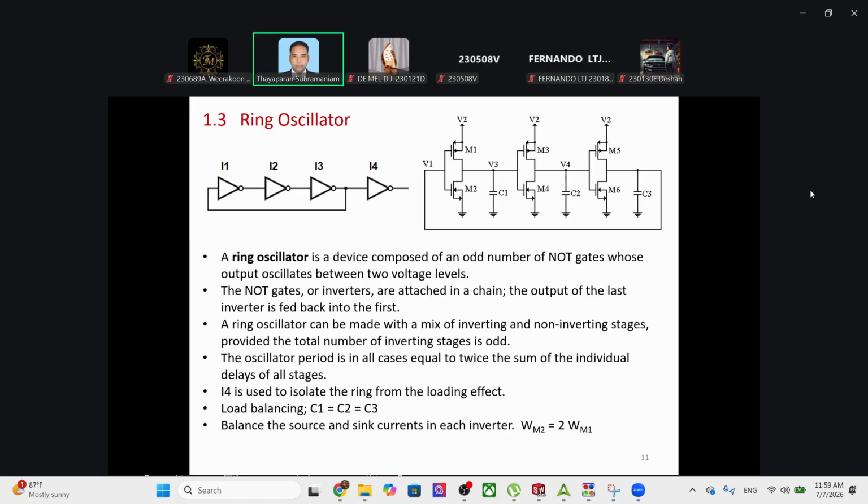You have the frequency, right? Suppose after designing, when you measure it, you will have one output frequency, but the output frequency will not be the same all the time. It has some plus or minus, right? That is what we call jitter, clock jitter.